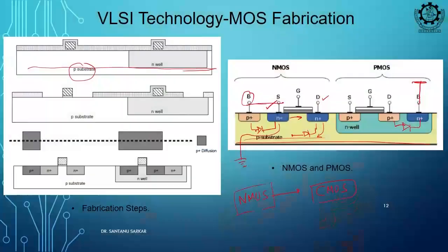If you see, just like that we draw some diode structure. These diodes are not real diodes, they are called parasitic diodes, because physically no such structure is there, but the junctions can make this kind of circuit component, right. Parasitics are like small elements.